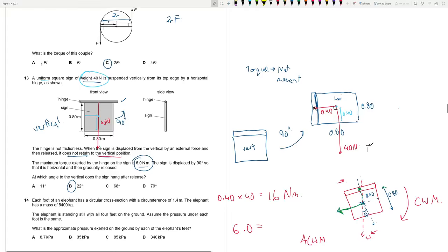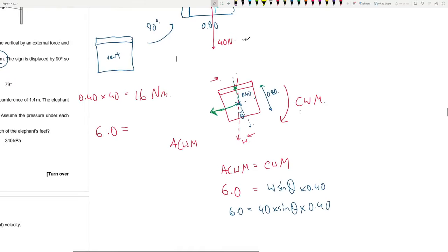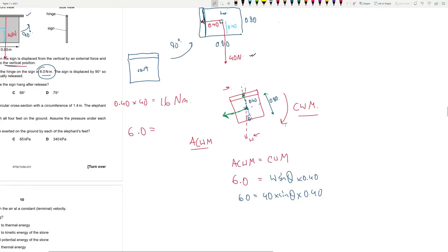So it's going to stop midway between these two instances that I've drawn. Not vertical, not horizontal, something in between. It's going to be something like this. It's going to stop somewhere here. It is neither vertical nor horizontal, somewhere in the middle basically. So let's see how I actually figured out where it stops. Since the weight is providing a clockwise moment, the friction will provide an anti-clockwise moment. So let's look at the figure step by step. I'm going to draw another one, don't worry.